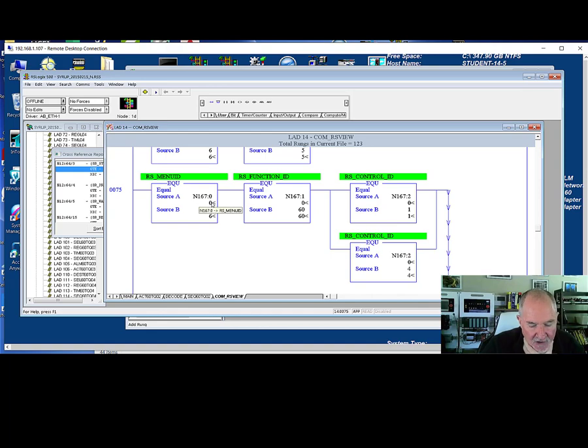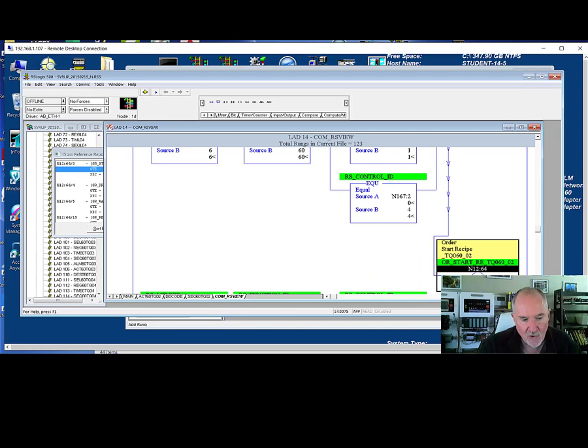So in this case, once again, I happen to know that this program interfaced with an RSView32 HMI, which is basically SCADA. It was a computer, and as people selected recipes and things, they would select a menu number and a function number and a control ID, and it would change these numbers on the HMI, and then that would issue the order to start the recipe.